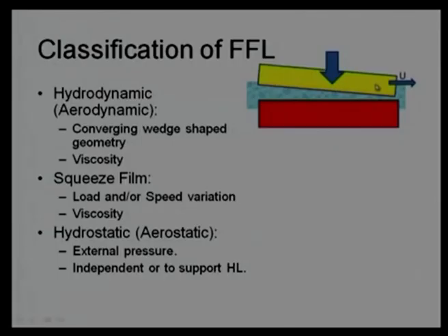You can see there is a wedge action. Thickness on the left hand side, or fluid film thickness at the left hand side is greater than thickness at the right hand side, and this convergence is coming in the direction of velocity. So, this fulfills a hydrodynamic action. There is a normal load, there is a relative velocity, there is a wedge action, and we are assuming this liquid is viscous.